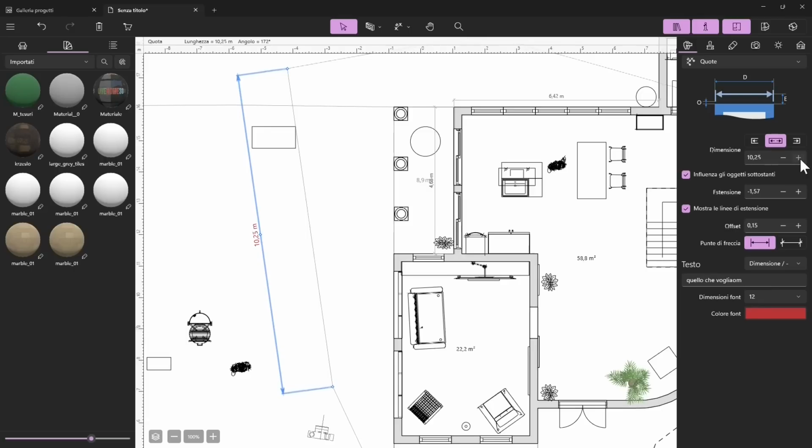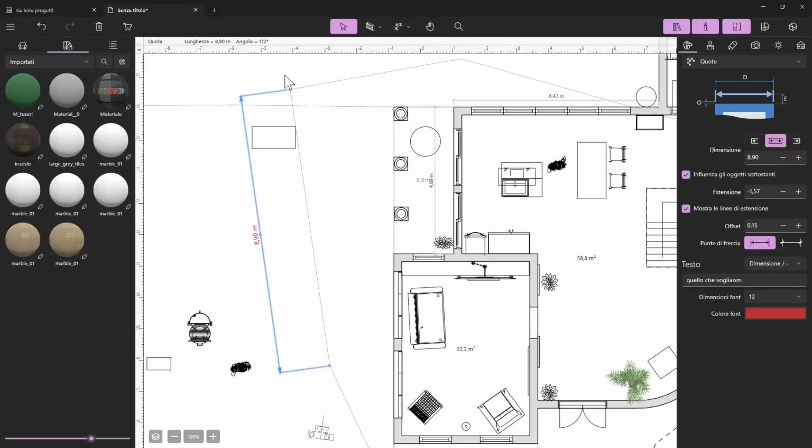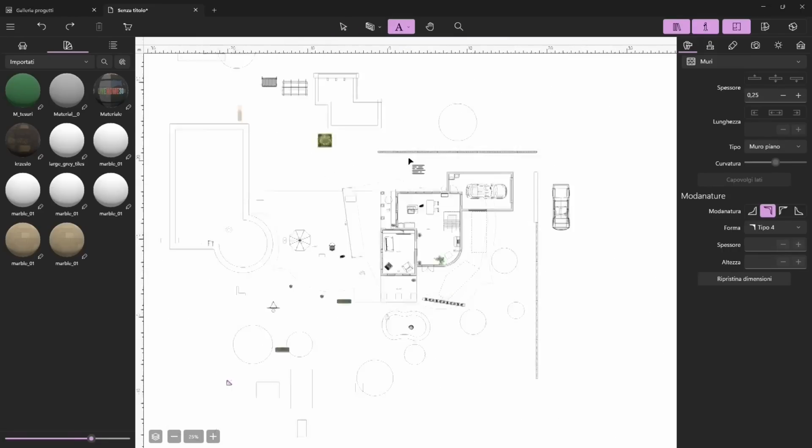Now let me expand again the annotation. You can see that if I change the length of the annotation, it is affecting the element that is being measured. So this is why we can lock the two. You can make the two dependent. So when you check that checkbox on, you can establish that connection.